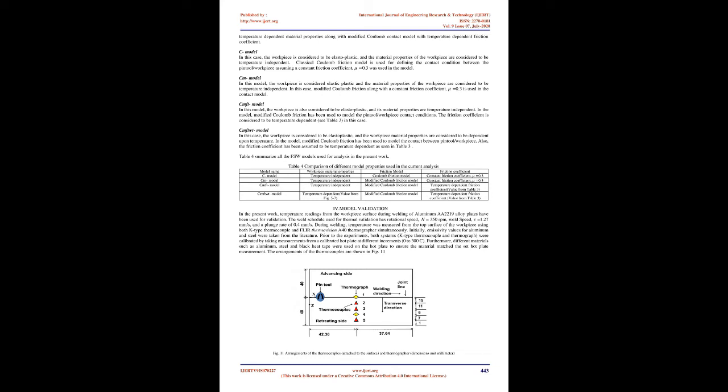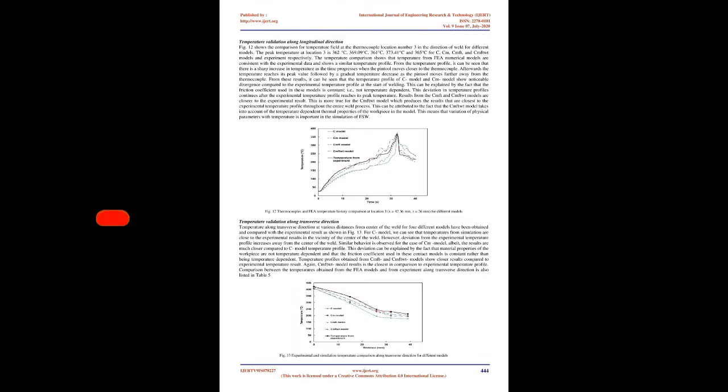τ1 and τ2 equal two orthogonal components of shear stress. In Coulomb friction law, τcrit can be expressed as a function of the friction coefficient μ and the contact pressure P, as given in the equation, where the fundamental assumption is that slip occurs when τeq equals τcrit. In a modified Coulomb friction law, the critical friction stress is limited by capping the critical stress to a maximum limit, as shown in equation 26.